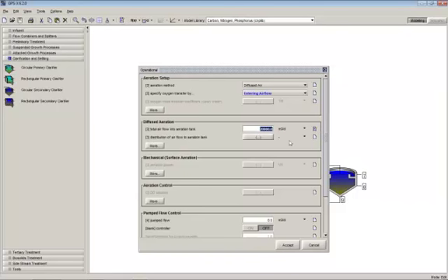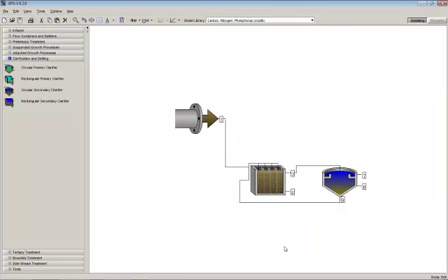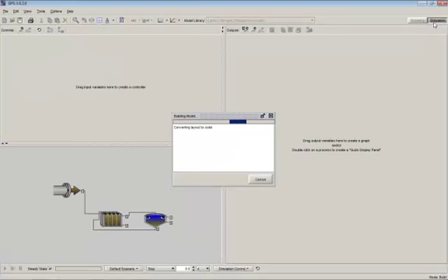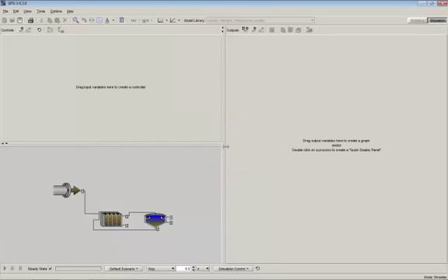So once you've done that, you've entered in all of the flow rates and recycle rates and wastage rates and so on, and specified all the incoming concentrations in your influent, you can go to simulation mode here. So this now puts us in a spot where this model is going to be built, and this is our Fortran compiler in action there. We use Fortran because it's robust and very fast.